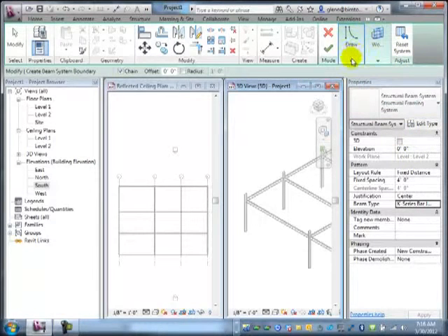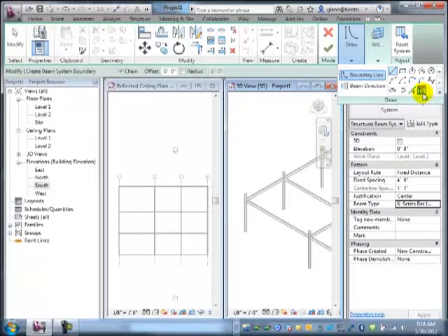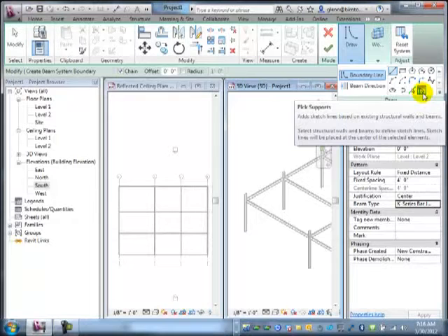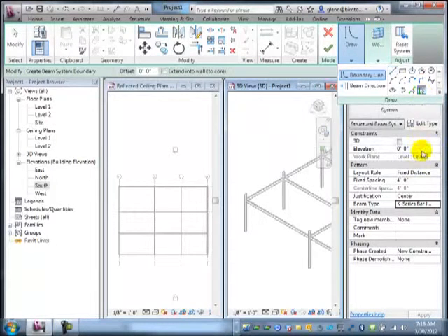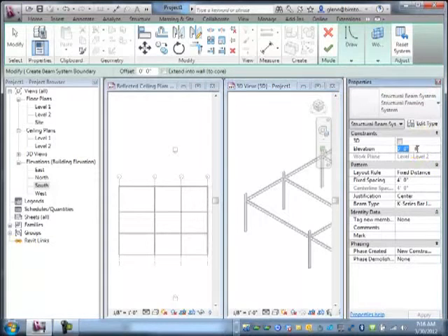But the easiest way to place things is, as Rima suggested, probably to use this thing where we pick an existing beam, because if you pick the supports, the nice thing is if the supports move, the boundaries understand to move too. Now, I'll do one other thing before I do the picking. For the elevation, I have to lower these that same 5 inches. So let me put that in there.